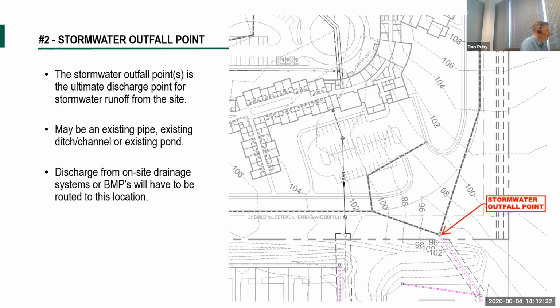The next point that we wanted to look at was the stormwater connections. So this site, this example that we're looking at, happens to be one that is part of a master planned development. So there wasn't a BMP shown on that site layout, which is good for the sake of we don't have to worry about setting aside real estate for that.